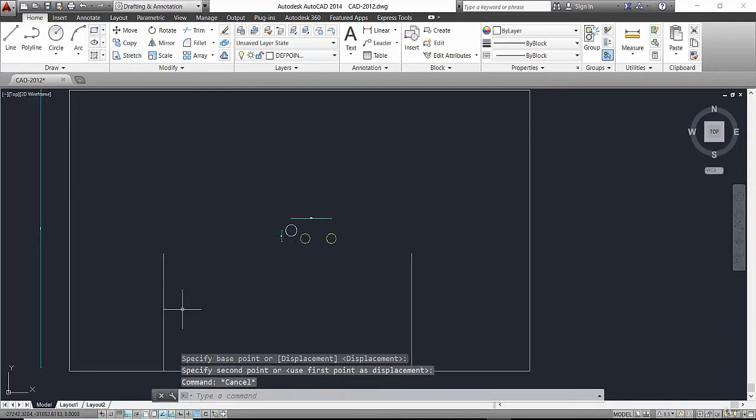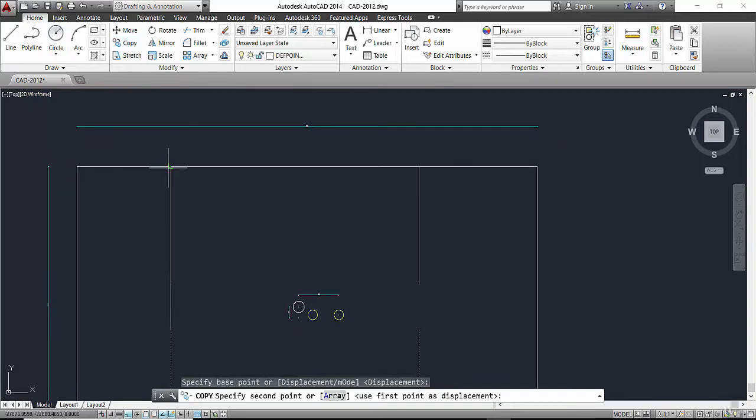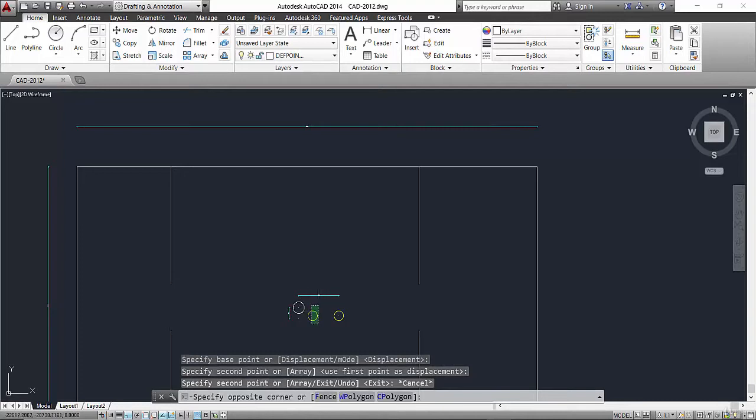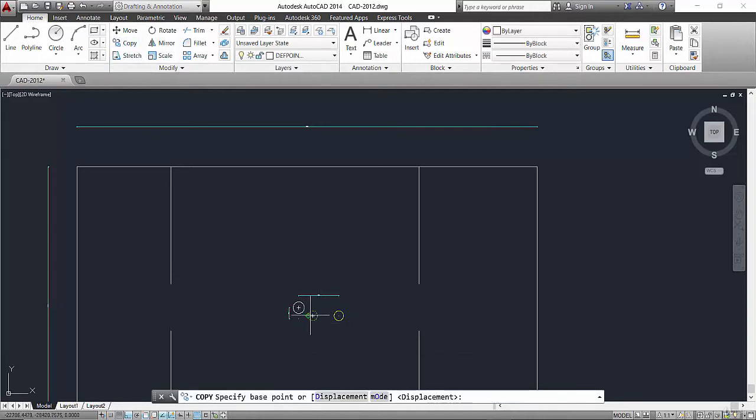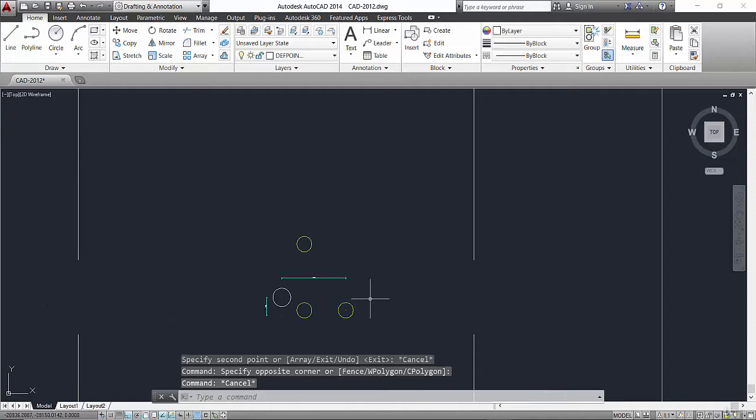And if we have shear walls here, the center of rigidity will move up. So the center of rigidity is related to the position of the shear walls. The more symmetrical the shear walls are in the plan, the closer the center of rigidity is to the center of mass.